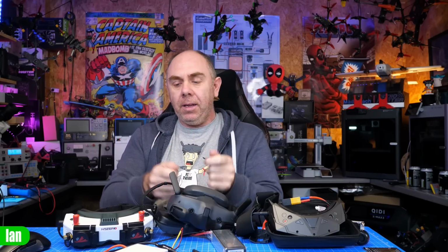Anyone who uses this with other systems and those systems get interference, that is not DJI's fault now. It is the fault of the receiving equipment on those systems, because DJI have created a mode that does exactly the same as HD0 analog. It only transmits on the channel. The only difference being that the DJI goggles do transmit. Now, DJI can't stop that because their system is a 2-way variable latency system, but you are going to be battling interference on systems like HD0 and analog simply because these goggles are designed to have lots of amplification, especially HD0, to try and pick up as much of the signal as it can.